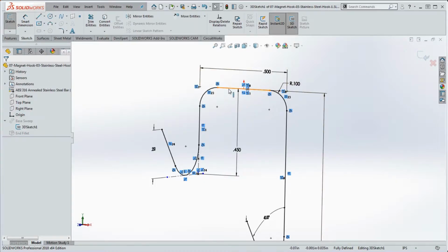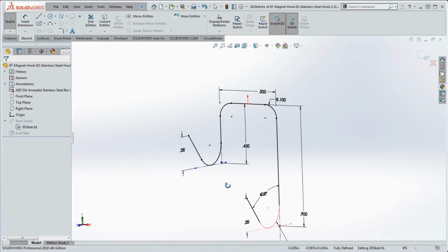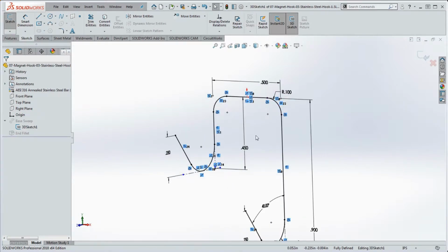So here in a 3D sketch environment, you can go in three different directions. You can't automatically assign horizontal and vertical to it because you don't know what to assign for that third element. So we use a triad down here, and what would be equivalent to a horizontal relation is going to be along the x. What would normally be a vertical relation is now going to be along the y. And the relationship that's coming out towards you is going to be along the z. So with that in mind, we're going to be putting this sketch together in a 3D sketch.